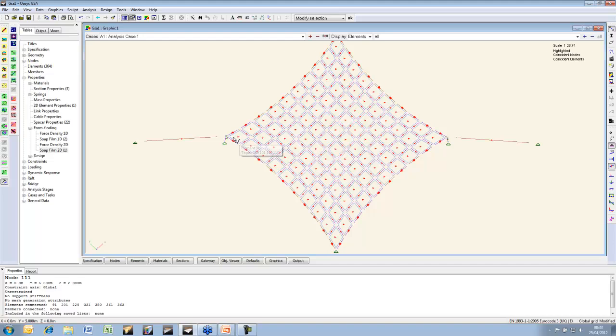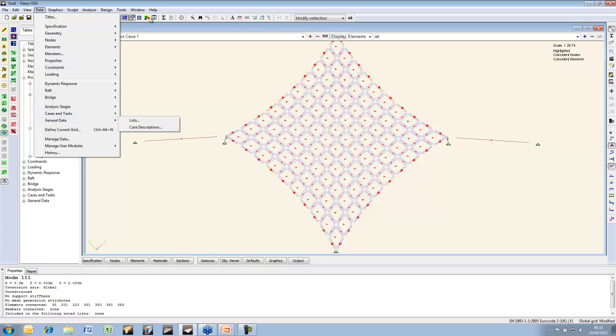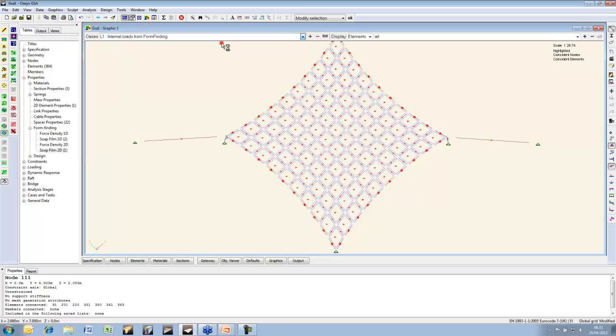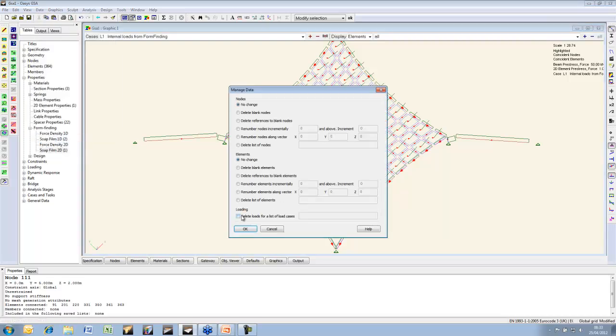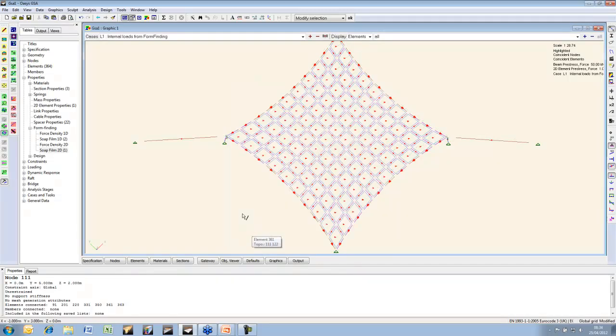So you see now the warp is going straight between the two posts. I'm also going to delete out the pre-stresses. Now you note it did create pre-stress forces. Don't want those, so I'm going to delete out, use the manage data, so they're all cleared away.